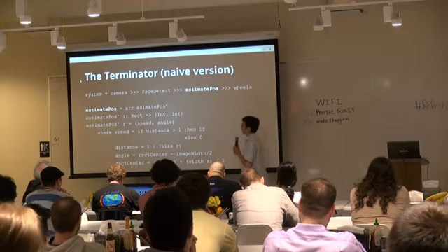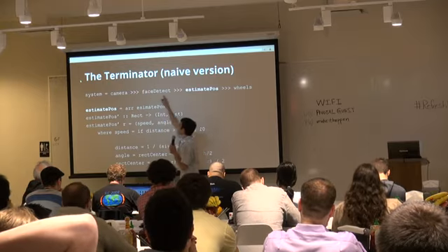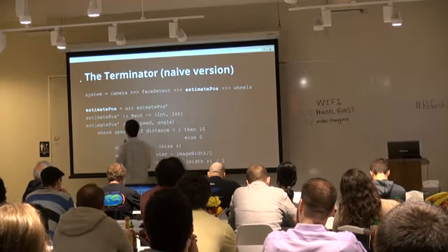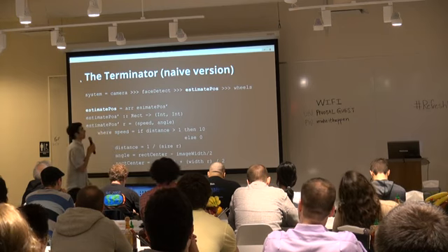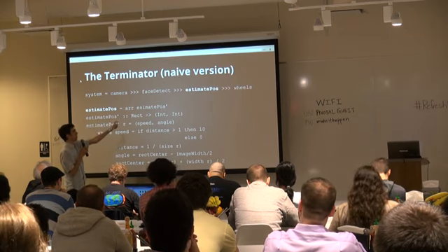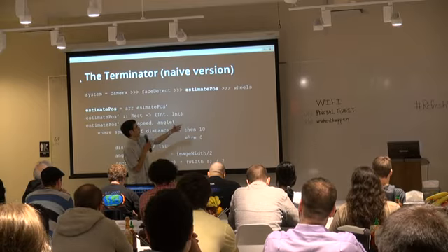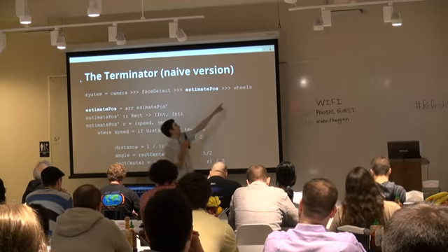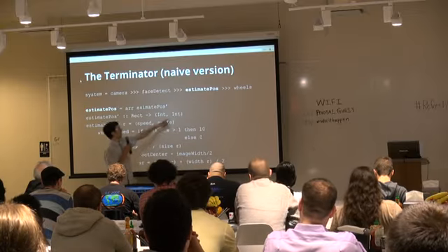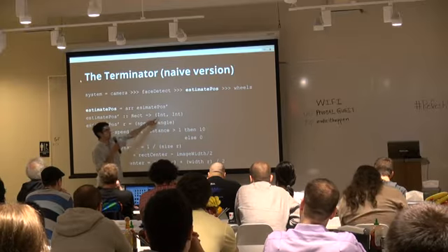Look at some code. So the system takes the camera, feeds it into this face detection, and we're going to assume that estimate pause is the function that estimates the position, and it should output to the wheels, which is really the robot itself, and this processor expects a pair of numbers which are speed and angle to which to move the robot. So if this is positive, we go forward.